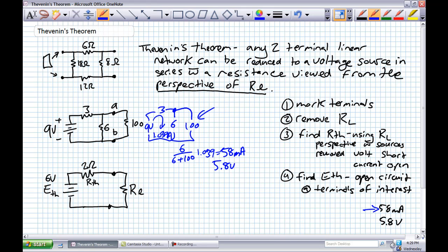And now here's the catch. Do that for another resistor. Do it for a 1.2K resistor for that same circuit. You would have to go through all 7 or 8 steps again. Here it is: 1, 2. Bang, I'm done. Okay? Now do it for a 2K resistor. Another 7 or 8 steps. 1, 2, done. That's the advantage of Thevenin's theorem.